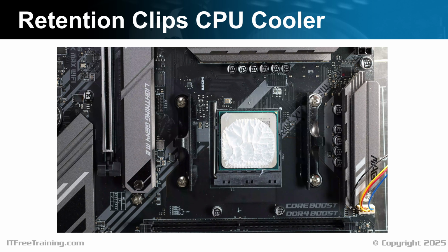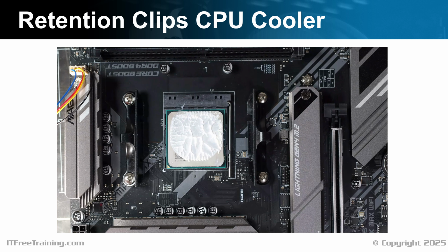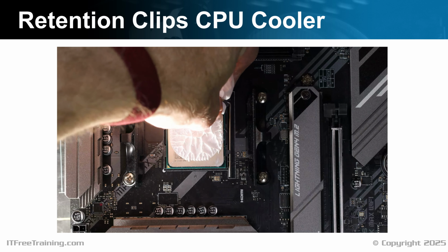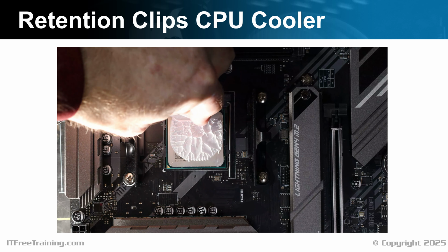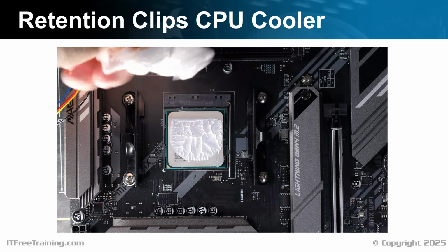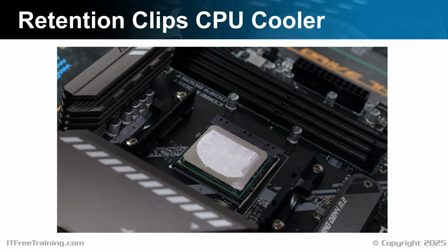You'll notice that the thermal paste spreads out, but some got a bit too close to the side for my liking, so I'll remove the excess from the side. It's not too bad and you can leave it, but I don't like to risk the thermal paste spilling over the sides of the CPU. I'll now replace the CPU cooler.